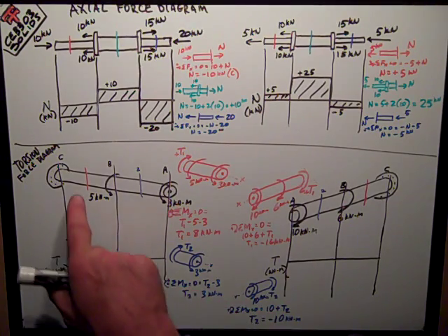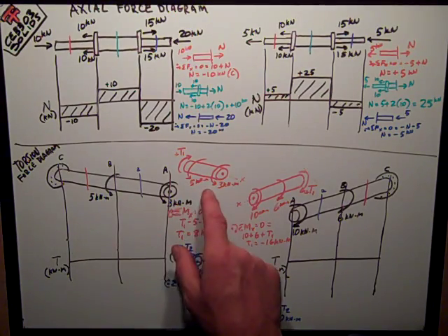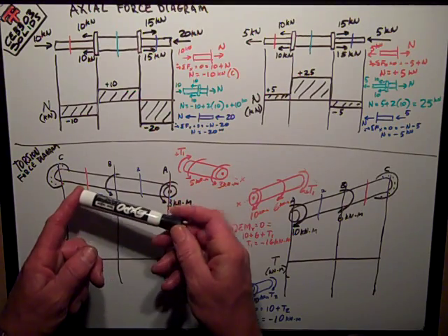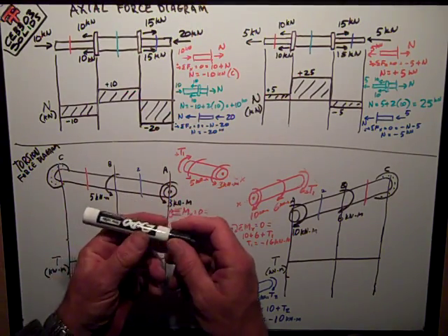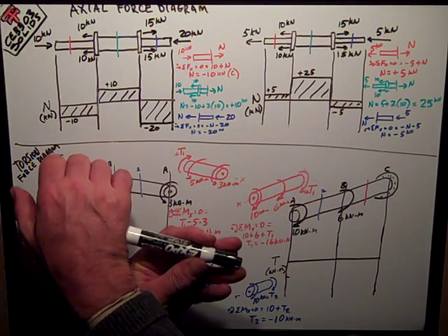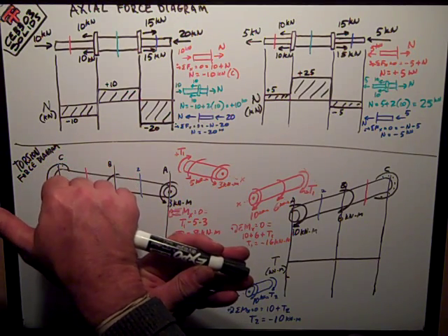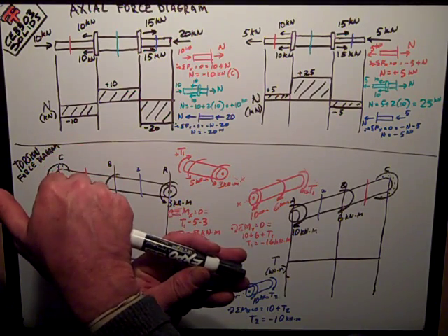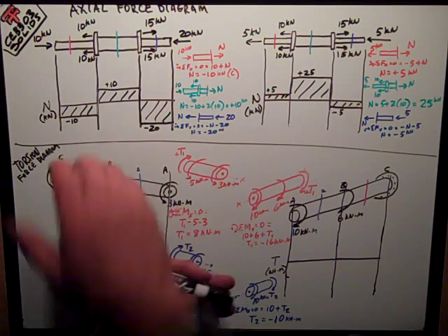And I want to cut a section in red. Red cut right there, my red drawing. I've got this shaft sticking out like this. I've made my cut right here. So I have to apply my right hand rule by putting the heel of my hand on the cut. Thumb points out away. My fingers curl in the direction of positive internal torsion. So they curve over the top.